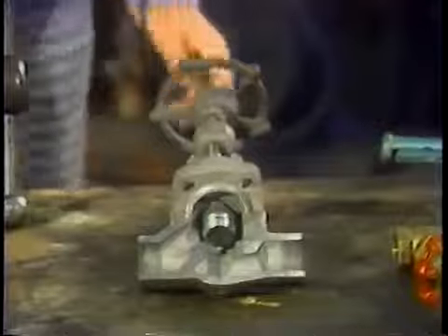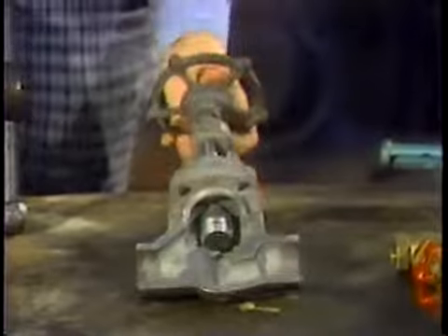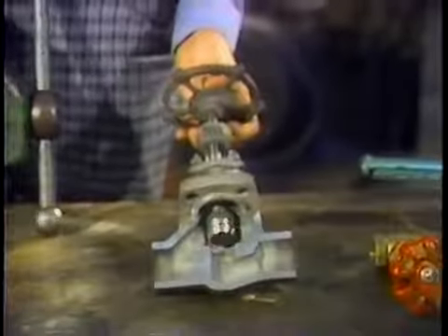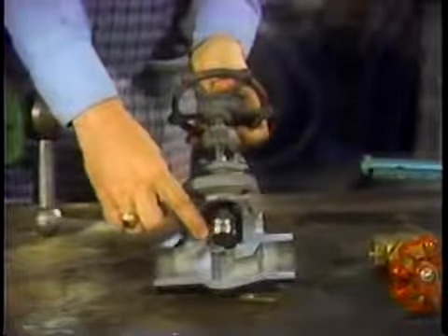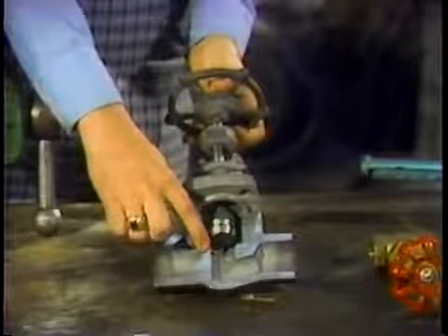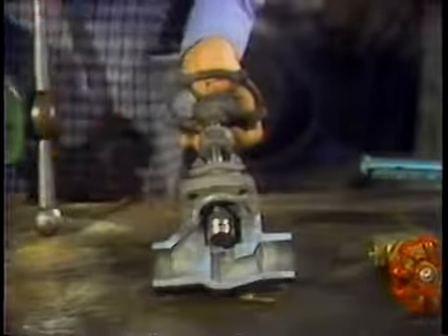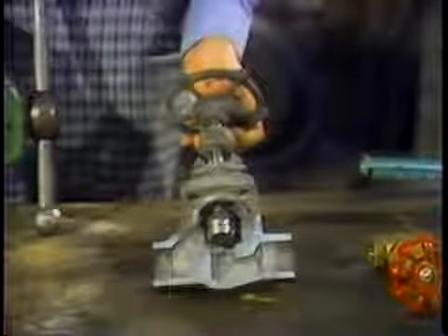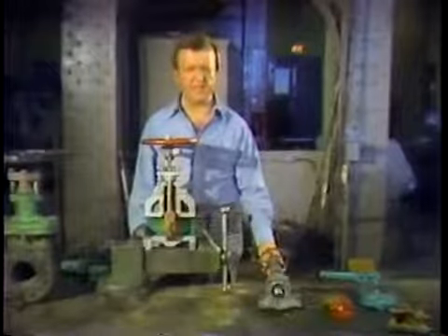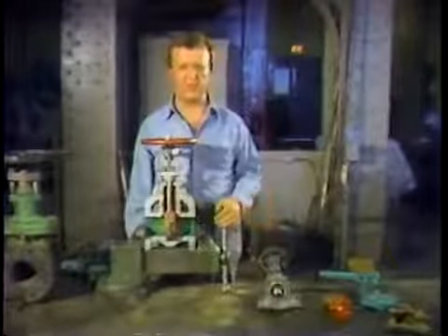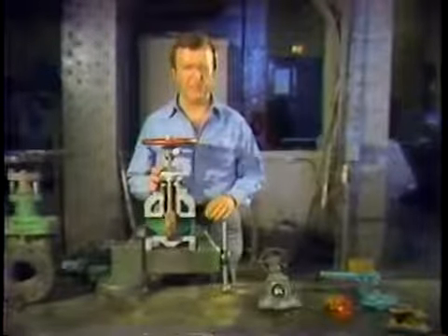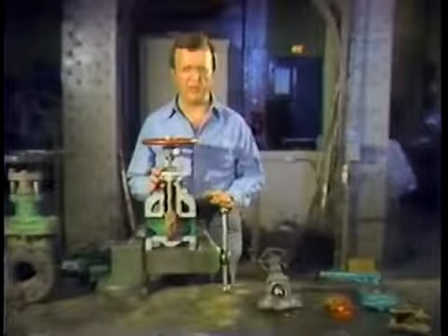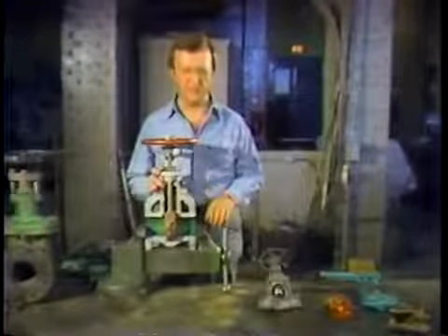The globe valve, however, can be used for regulating flow. It's often called a control valve. The shape of the disc and the arrangement of the seating areas distinguish a regular globe valve from a control valve. By its design, the globe valve provides a tight seal where heavy-duty throttling is required, such as in a high-pressure steam system. Throttling is reducing the flow without fully stopping the flow.